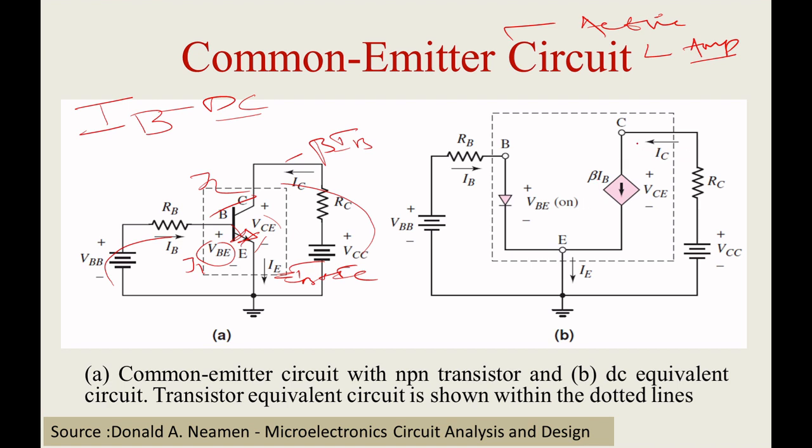The arrow is coming from collector to emitter, the collector is looking at the emitter, keep that in mind. This is your input biasing and this is your collector biasing, and RB is a limiter resistor connected to the base terminal. The skeleton of the transistor was simply redrawn with respect to the DC current concept, and I hope you understood this model, right?